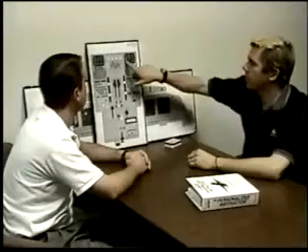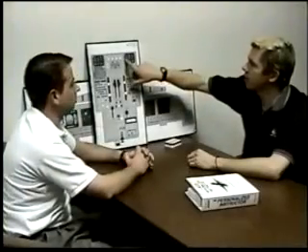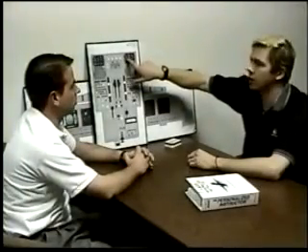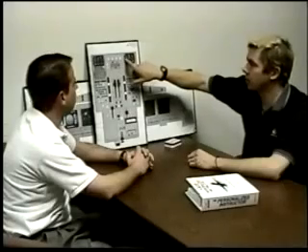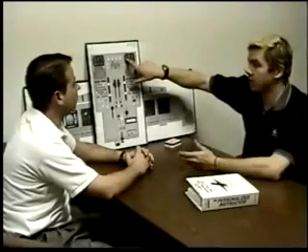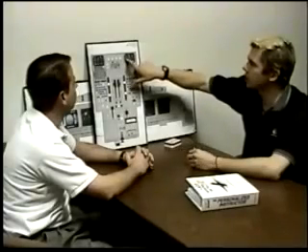What would be our minimum ground speed? Well, minimum ground speed is calculated by taking your V approach and then subtracting out 100% of the headwind. And in this case, at 330 at 15, that'd be 15 knots. So 138 minus 15 is going to be 123. That was the approach for the 320.